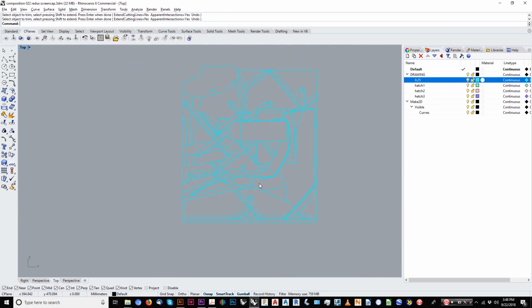There's also other commands such as fillet that you can use to kind of close certain curves. So what fillet does is, if you have 2 curves, so fillet, it basically, and if you do it with a radius of 5, for example, then you get that kind of scenario.